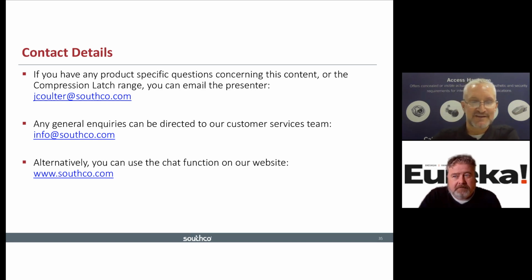That's a great question. First of all, a lot of the common modifications we receive deal with security. A lot of customers want their applications to have a unique driver head style, which may not be common in what's offered today. And therefore, a lot of the modifications we get will be to implement a specific tool function that they use in their industry that's not readily available. Also, we see a lot of our customers requesting specific key codes for their locking applications. Similar to your car, a lot of applications may want one key to start their car, open their glove box, open the outside door, and open their trunk. And a lot of customers want us to code our latches to their unique key usages so they can have the same common key among their applications.